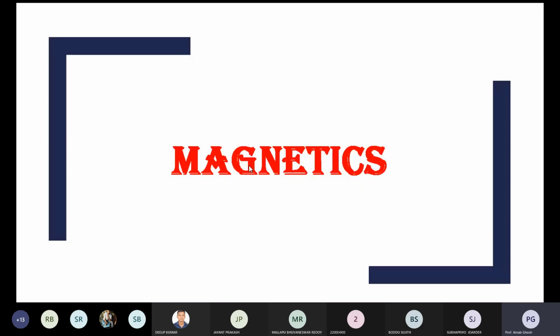So there is a problem of core saturation, so a special type of transformer has to be designed. Special type means only that you are changing the material of the core. Some data sheets are available on the internet from different small companies that manufacture cores for switch mode power converters. There are ring type cores, bar type cores, also E core, EI core. Different types of cores are available.